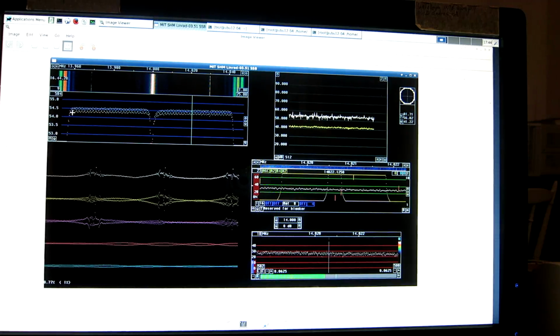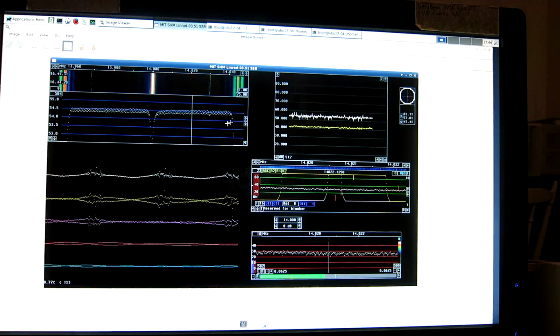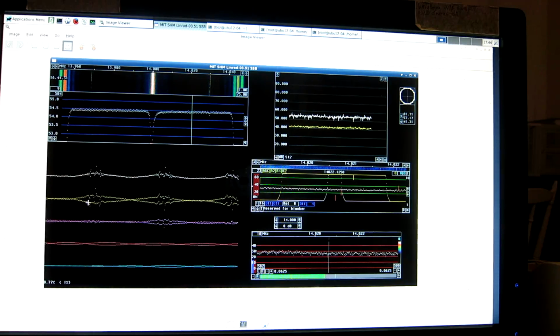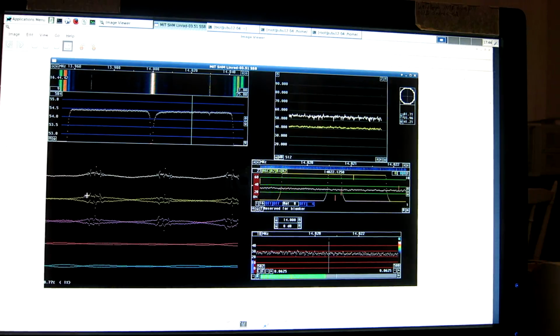So high frequencies about near the corner here, 45 kilohertz perhaps, and 45 kilohertz here, they don't have the proper phase relation. That's why we see a fairly strong signal near the Nyquist frequency. Every second point differs from the neighboring point.